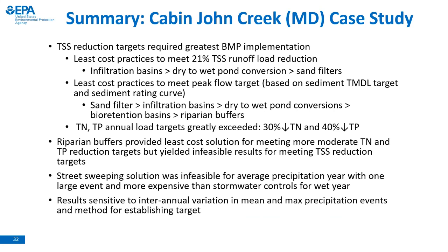And they looked at the relationship between flows and sediment loads using a sediment rating curve. This is important because a lot of the sediments in the system are coming from stream bank erosion. So to meet the peak flow target based on their process, sand filters were most important, followed by infiltration basins, dry to wet pond conversions, bioretention basins, and finally riparian buffers.